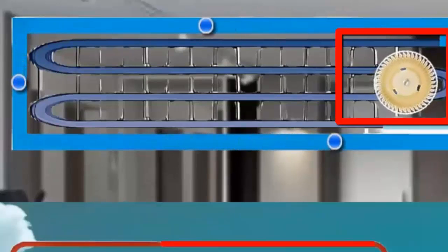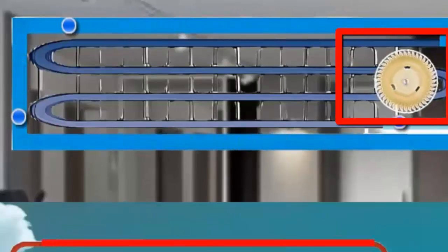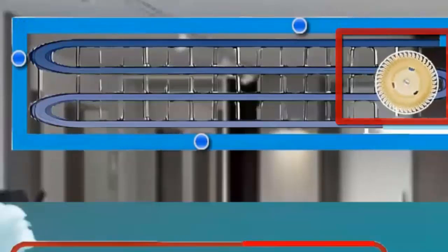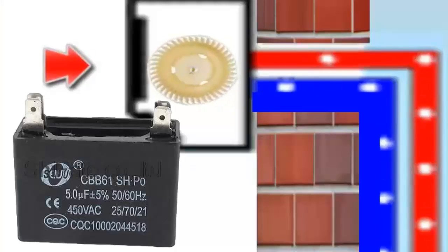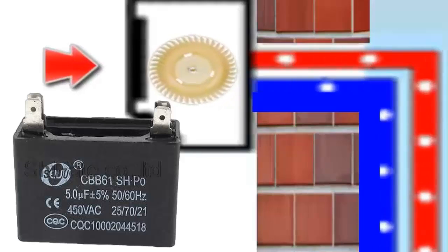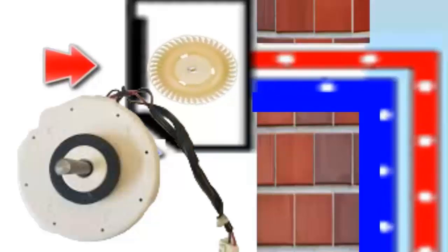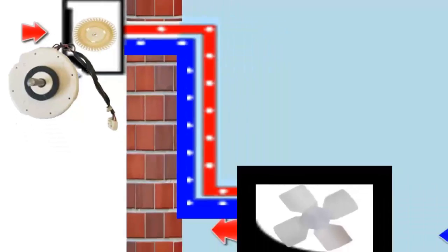11. In case of dirty filters or a dirty turbine, it is recommended to clean the indoor unit. If the fan speed is low, check the type of motor of the fan. If it uses a capacitor, it can be tested by changing it to see if the fan speed recovers to normal values. It is worth noting that a low speed of the fan motor can also be due to motor bearing issues.